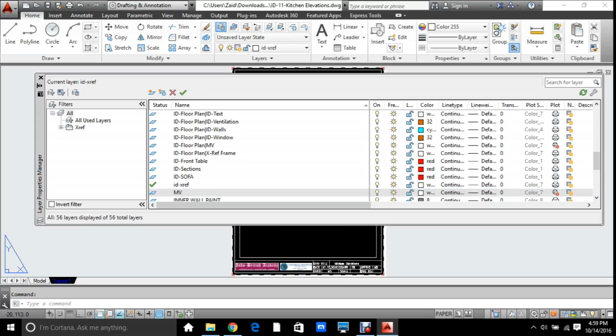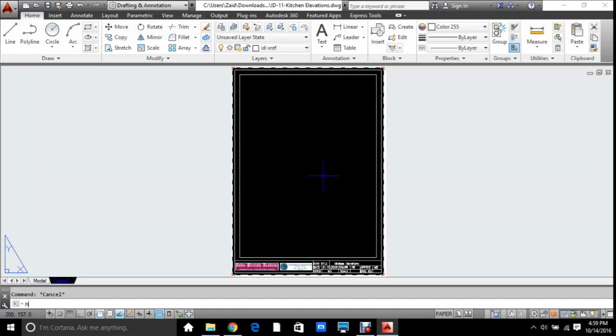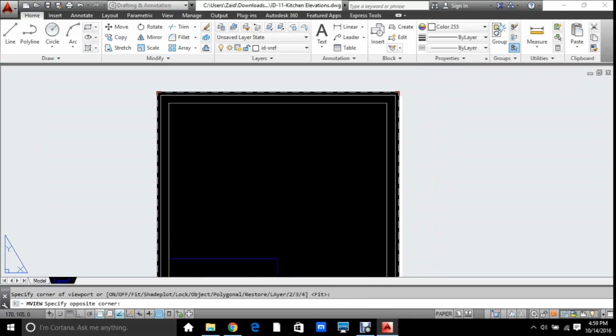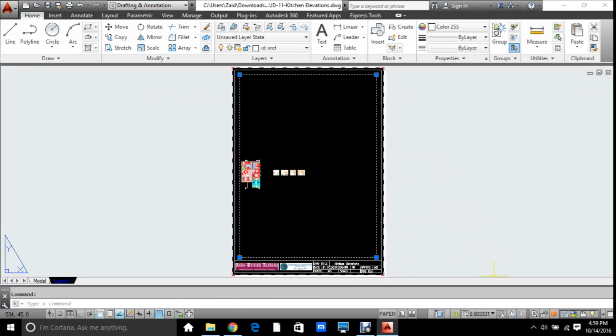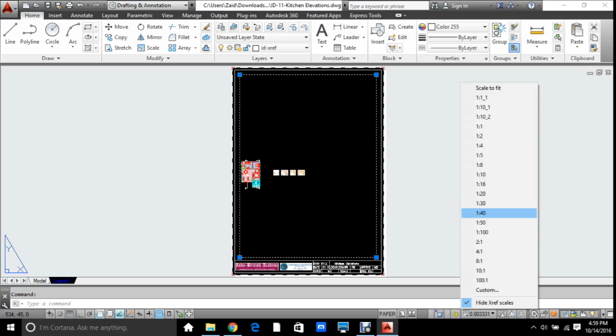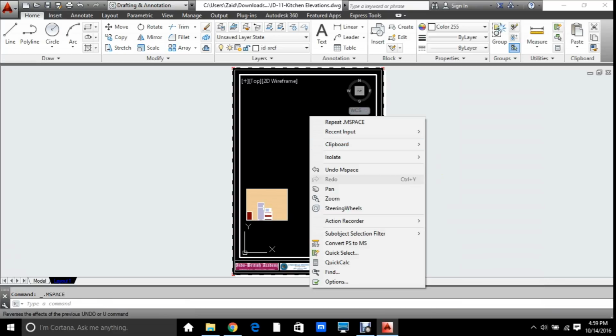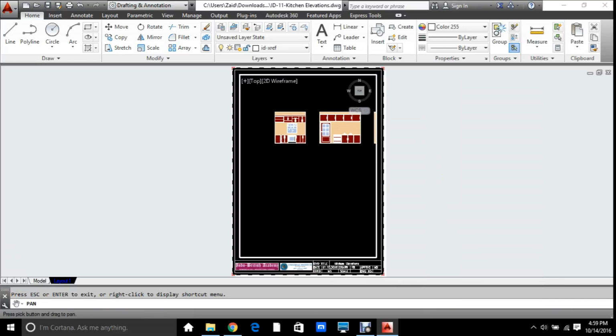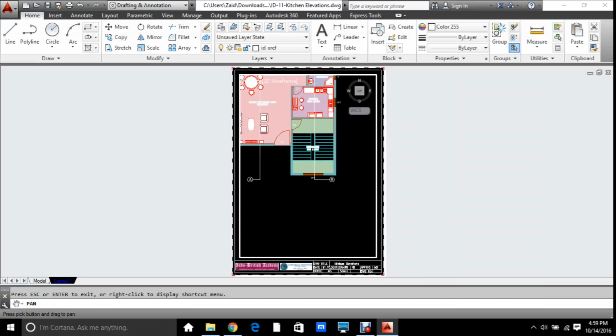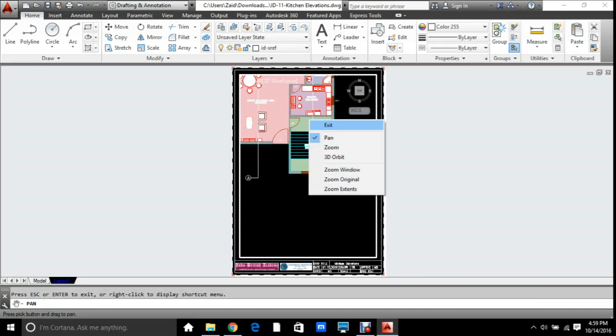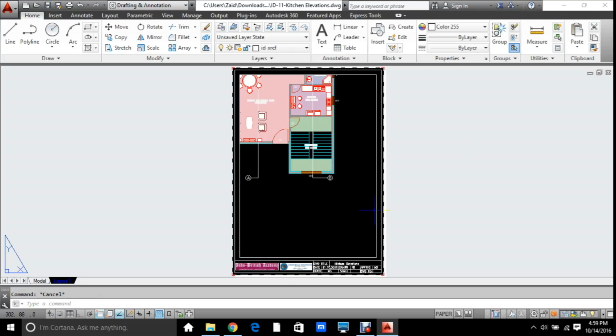and click on the non-plot, okay. The same thing, MV, make from here to here, then E, enter, select the viewport, go to the scale 1:50, click inside, use pan. I need the kitchen now, okay, this is my kitchen. Right click, exit, click outside, click MV, okay, see, this should not be free, this should be straight, that means ortho, you will press ortho and go straight.